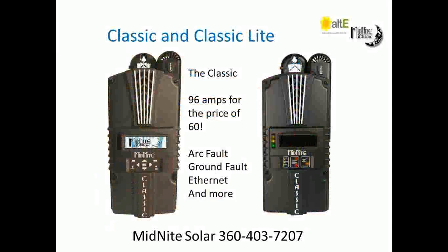It's a very elegant solution, and the benefit of it is there are no hubs, no switches, nothing. It's standard 4-conductor phone cable, standard RJ11 jacks. Literally off-the-shelf phone cable right from Walmart to plug these things together if you want to. We do sell networking cables as well, and you can build your own out of Cat5 cable and RJ11 jacks, but it is literally off-the-shelf phone cables and can stack up to about 240 controllers in one Follow Me loop. The limitation to that number is the Modbus addressing.